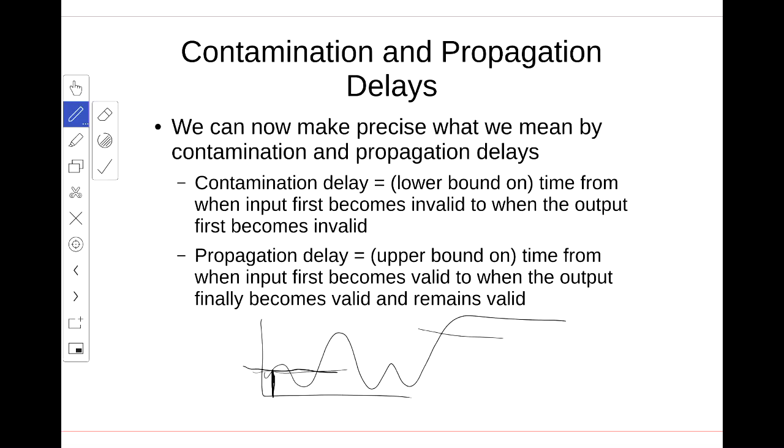But anything lower than V output low, or anything above V output high, is valid. So the signal at the output can change in the analog world without changing in the digital world. It only changes once it goes from valid to invalid. And that is the precise time you use to measure these delays.